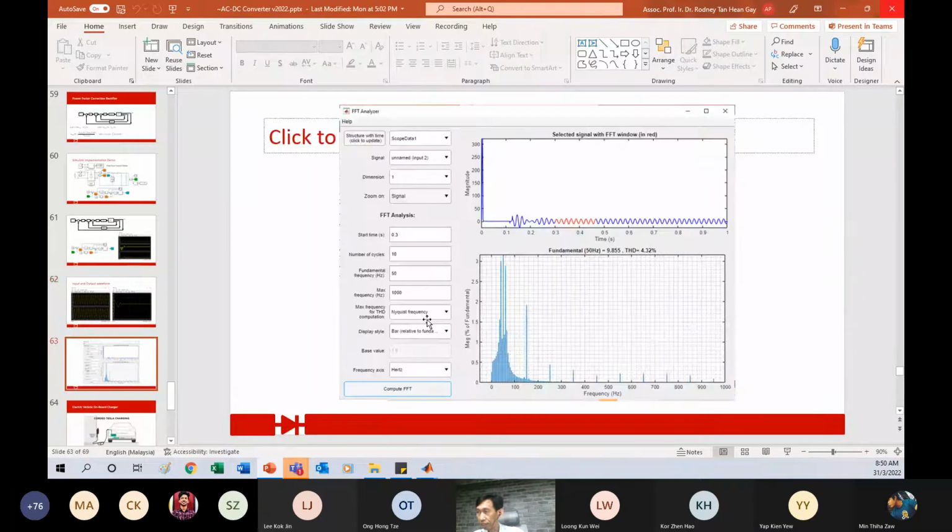The THD you can see is around 4, so less than 5. Of course, initially you will have a spike, because as long as you have PI control, be it single loop or double loop, unless you tune it so well that it won't have overshoot. For me, I just tune a few values that can get my output, that's all.